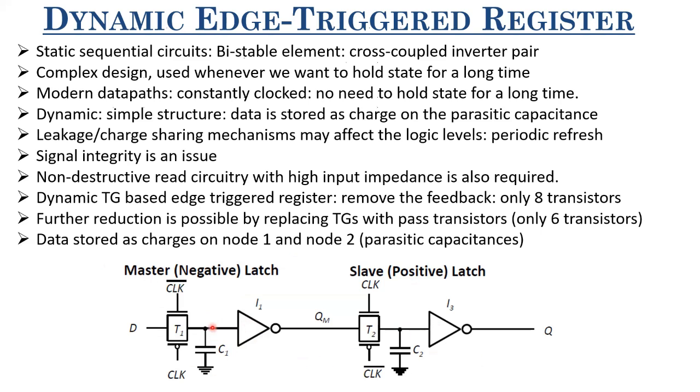First we have the input gate capacitance of this inverter, which is the gate capacitance of the NMOS and PMOSFET. Also we have Cint of these two, the NMOSFET and PMOSFET, which includes CGT, with the Miller coefficient times the CGT. Then it also includes your CDP and so on. So this capacitance is basically the sum of all these capacitances.